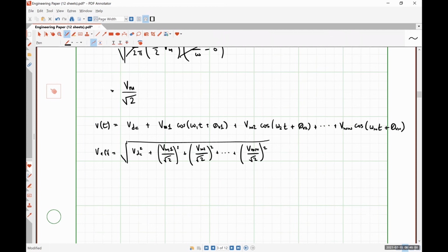So would we ever be asked for the instantaneous power? So the instantaneous power, typically speaking, is unimportant. There's only a couple of times where it's ever really going to be a big deal, and that is inrush in an electric motor and things like that.